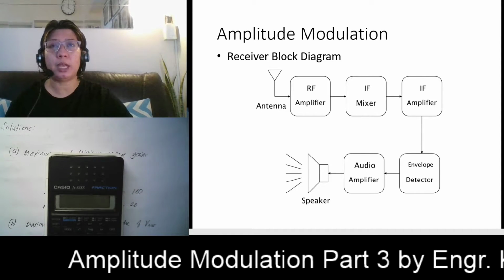Actually, this envelope detector here is our demodulator. So we will be discussing the demodulator in our next video. Afterwards, since the signal was already demodulated, that means from the intermediate frequency we have already recovered your original signal in the audio frequency range.